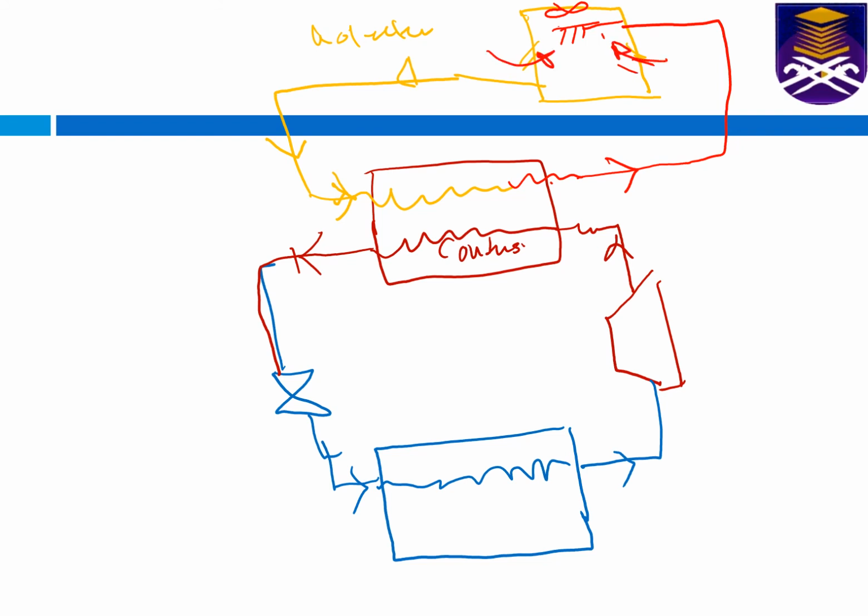Okay, and here you have, let's say, the cycle for the refrigerant. This is a cycle for the R134A. This is a wet cooling tower. So the wet cooling tower, the cool water outlet is used in the heat exchanger for the condenser. Why does the condenser need that? Because it requires higher capacity for the cooling process to take out the heat from the chiller.